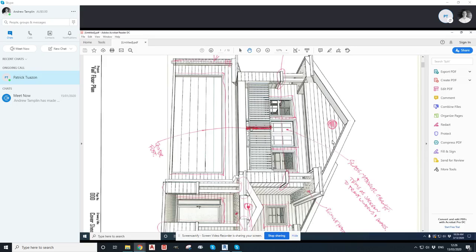So there's two ways to do it. You can either edit the railing or edit the railing type. You have to go into its settings and create a pattern that puts the post in there. Or you could put in a column and then create two railings either side. Does that make sense? You would have one railing on one side and one railing on the other side of that middle post.